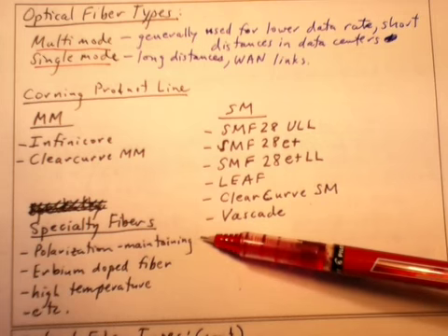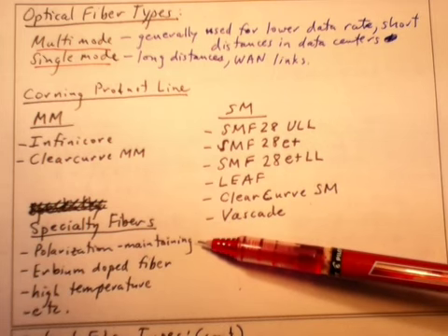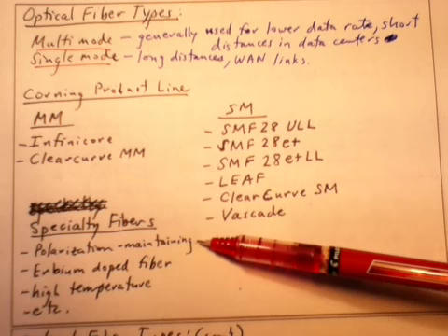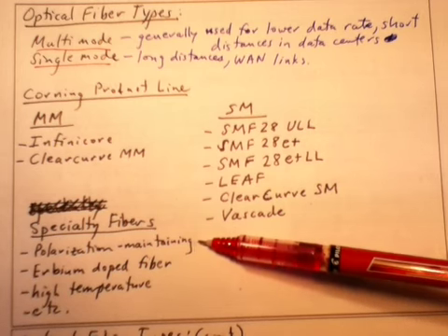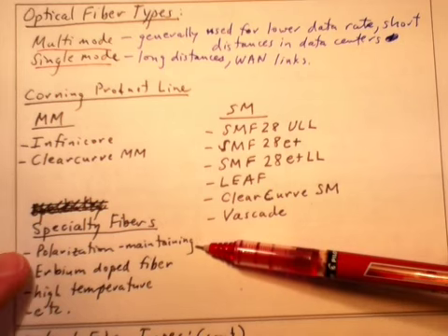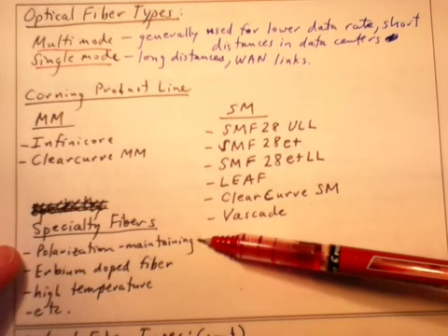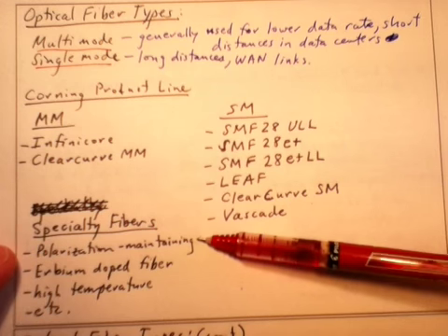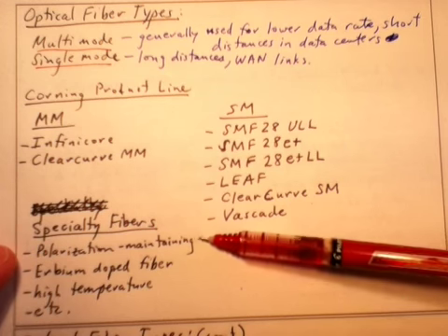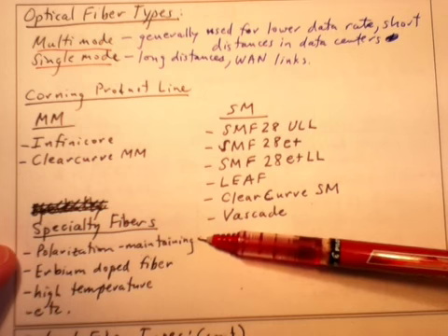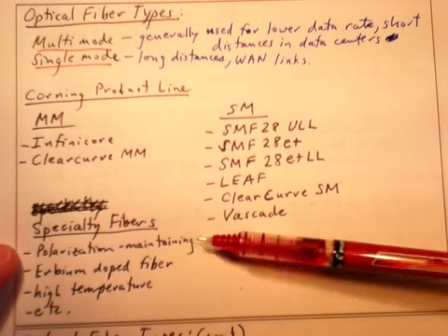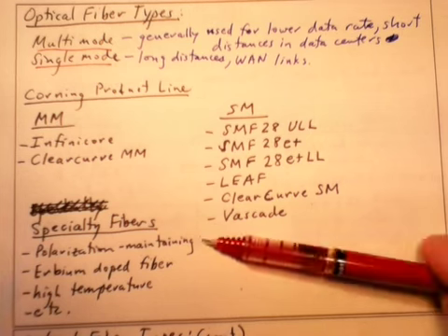If you go long distances, generally speaking, you're going to get a whole mixture of different types of polarization states: circularly, elliptical, linearly polarized, and so one would say that the light is not polarized on the way out. And for various applications, especially in fiber optic components and fiber connects between integrated optical components, polarization maintaining fiber may be needed.